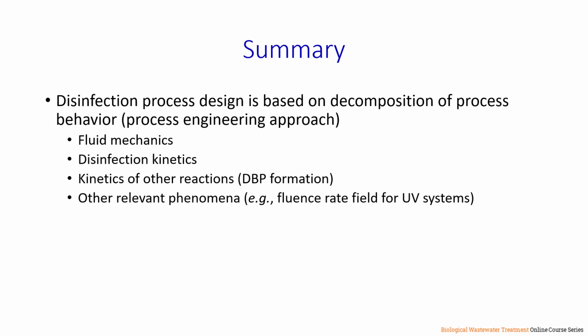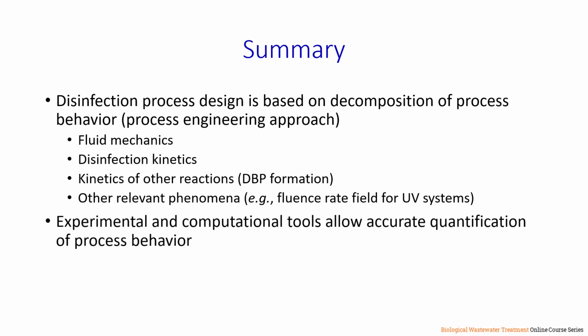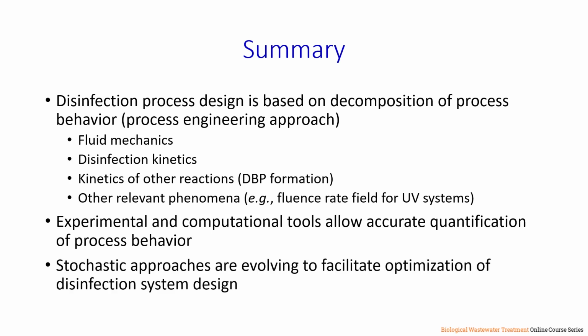Those include fluid mechanics, disinfection kinetics, the kinetics of other reactions such as disinfection byproduct formation, and other relevant phenomena, for example, in the case of UV systems, the fluence rate field. The experimental and computational tools that are available now allow for accurate quantification of process behavior. And in fact, stochastic approaches have emerged over the last few years to facilitate optimization of disinfection system design and to incorporate variability.